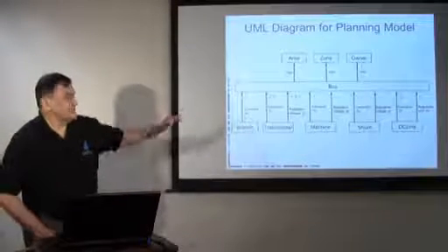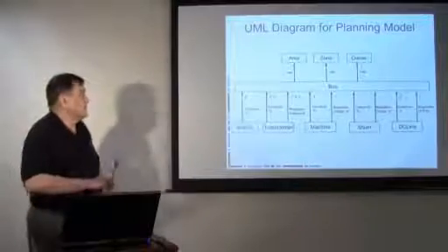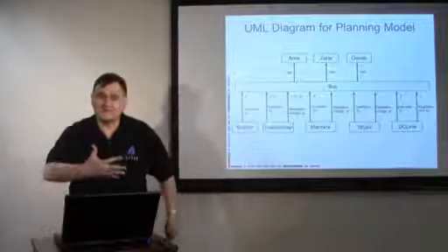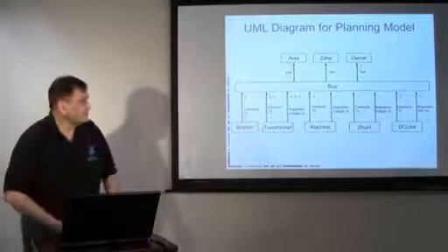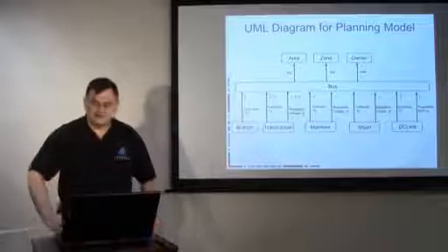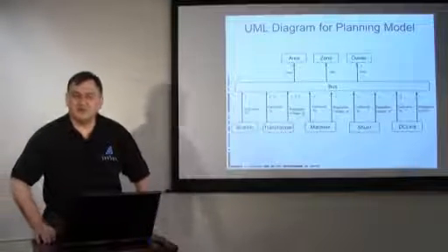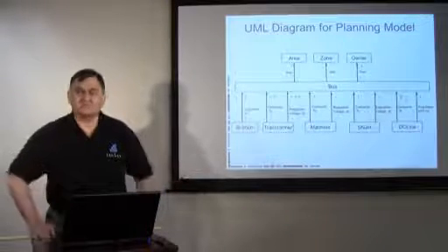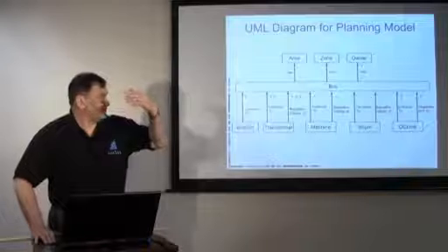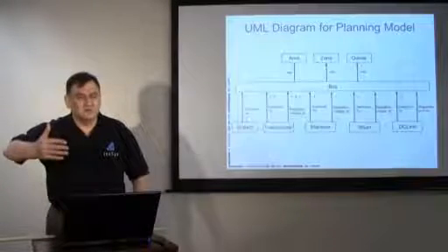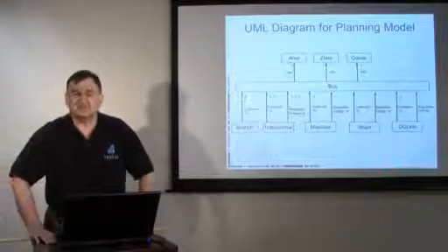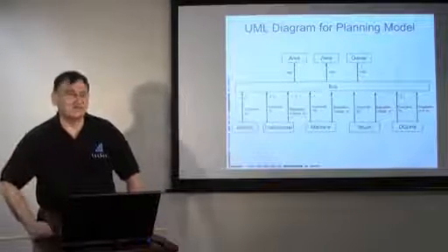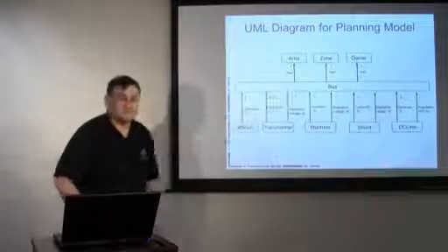Now, the one thing we notice about this is that this abstract concept called the bus is at the heart of everything. Everything is connected to a bus. Everything is regulating a bus. And that one thing greatly simplified the development of the early planning power flows. Basically, it meant that we could number all the buses in our system, and not only did we have a way of identifying those buses, we could use those buses as indices inside our computer software, and everything became greatly simplified as a result of the fact that everything was attached to a bus.